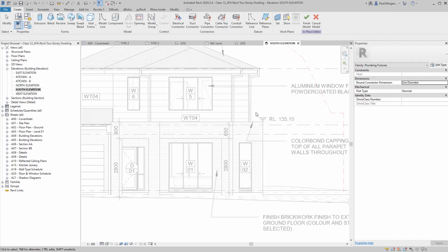All right, now that's done, everything grays out, and you can see I can't select anything because I'm in this sort of modeling environment. You'll notice the ribbon now looks a lot like a family editor. It's like I'm in a family editor, but inside the model environment, not separately like you were with your joinery and casework. From here, I'm just going to use an extrusion.